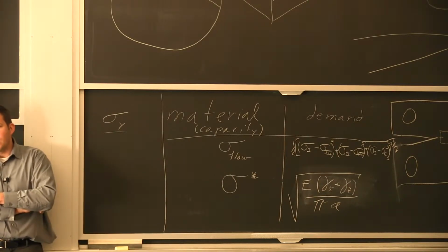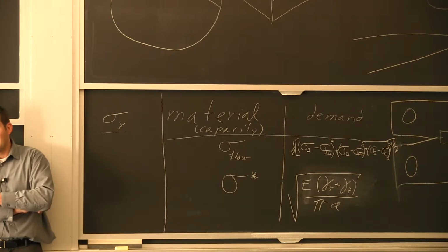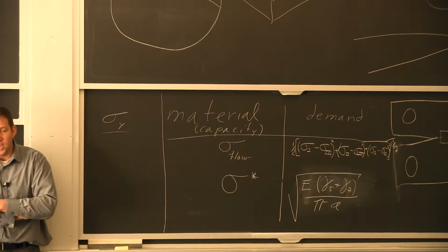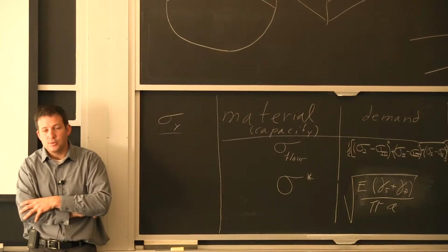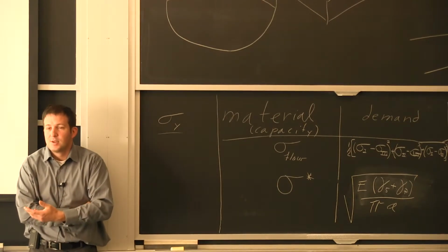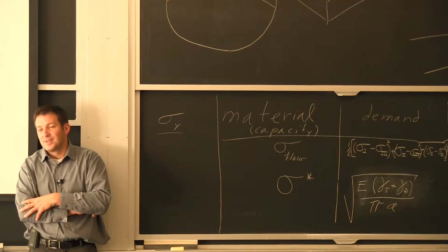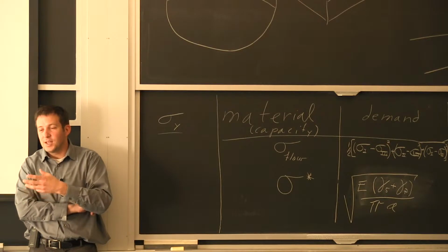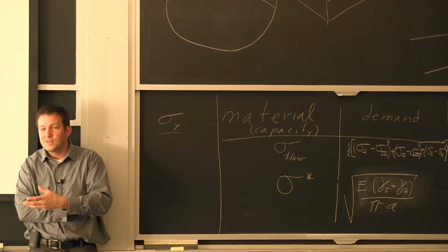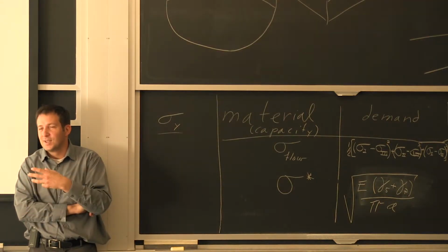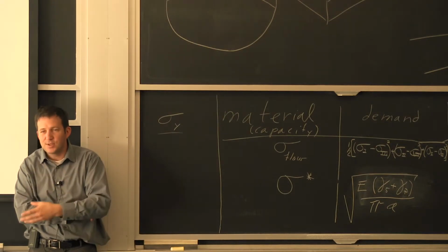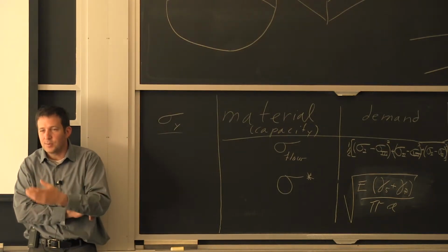With aluminum alloy, probably the easiest way to think about it here is, I told you there are more slip systems. So it's very hard to think of the aluminum alloy just completely losing the deformation. It's going to harden, but there's always going to be some deformation taking place.